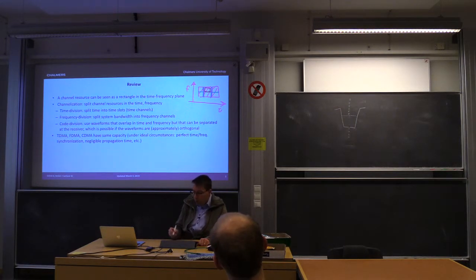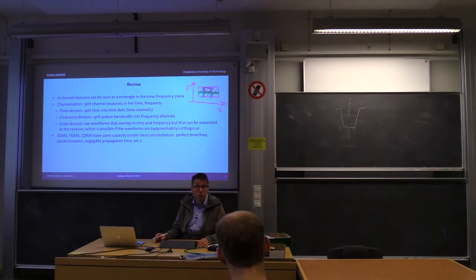And we also need probably to put in some guard intervals here, small frequency buffers between the different channels. Guard intervals in frequency when we cannot use the channel for this. And this has to do with imperfect filtering and things like that. So there are many practical constraints to this, which somehow favors one type compared to the others.